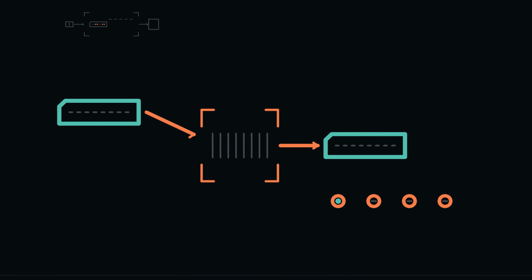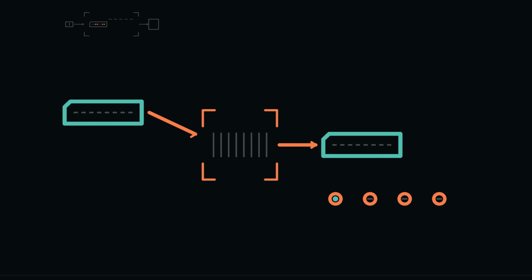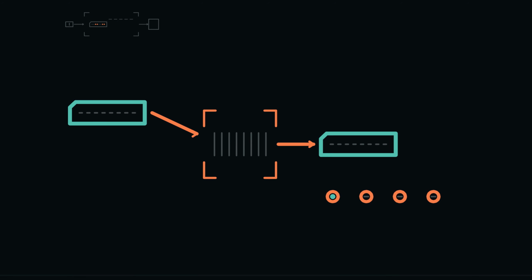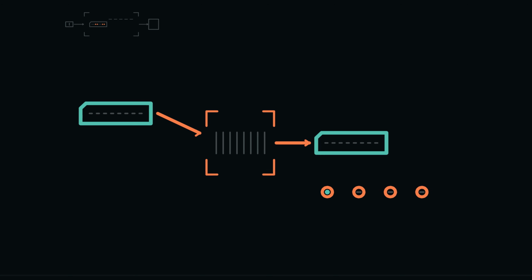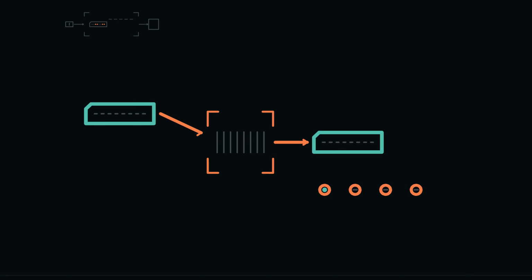Zero is 1 exactly when all 8 result bits are 0. Negative copies result bit 7. It reports the top bit, which indicates a negative value only under the signed 2's complement interpretation. Carry reports carry out for addition, no borrow for subtraction, or the discarded bit for a shift. Overflow reports that a signed addition or subtraction crossed the representable range.